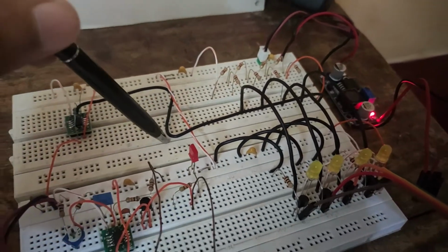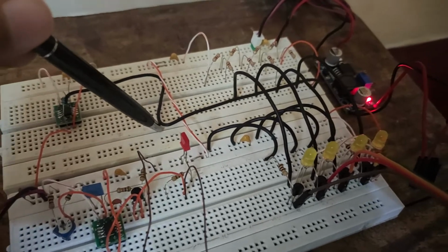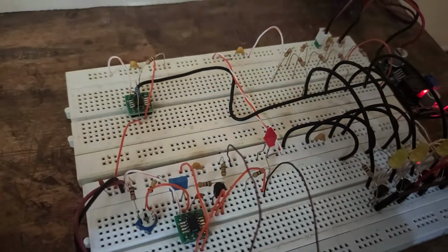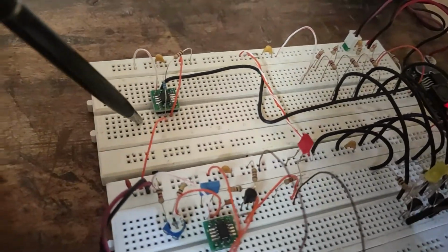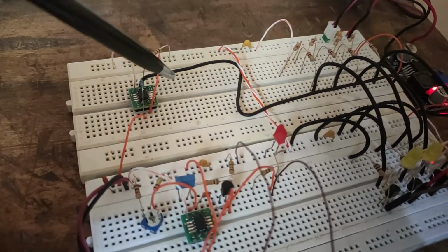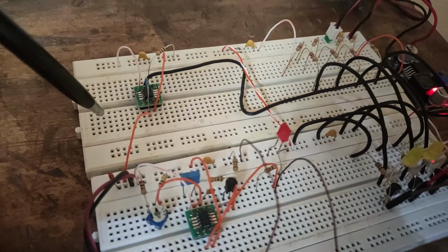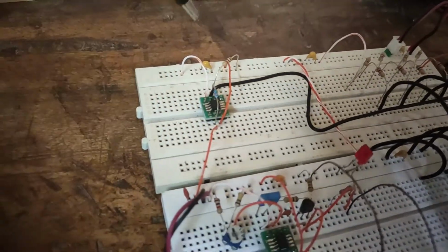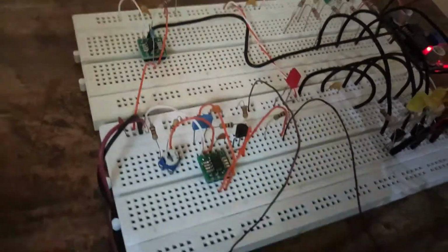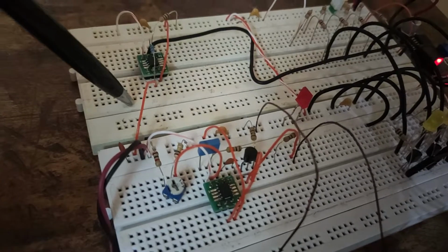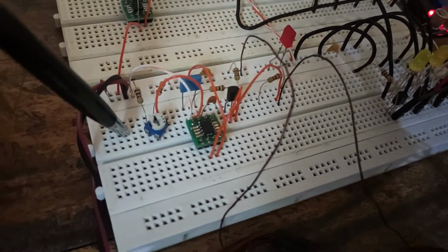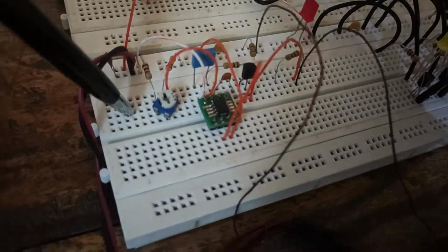This analog voltage is not specifically in 0 to 5 volt range, but to condition this for the transmitter, we need it in 0 to 5 volt range. So I have put up a simple non-inverting op amp which would take in any of this voltage and convert it into 0 to 5 volt range. Yeah, these are the power supply decoupling caps. Then, having a perfect 0 to 5 volt range, we feed it to this current loop transmitter circuit.